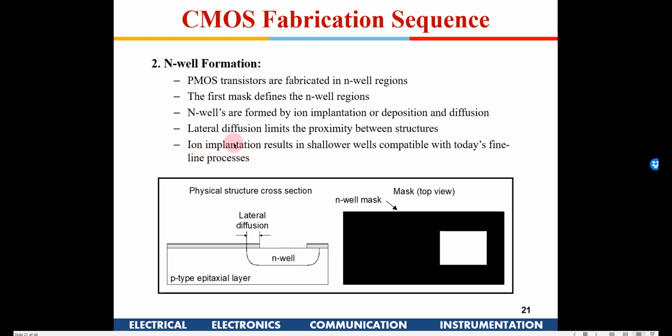Now the advantage of ion implantation: Aman Jain had asked, probably, why not diffusion, why implantation? Ion implantation is more controllable because it is done through an electric field, and we are accelerating and pumping the ions. So we can control the depth in a much more controlled manner when we are using ion implantation rather than diffusion.